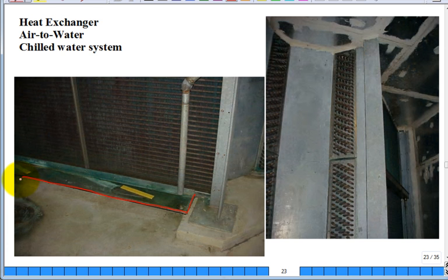What do you think that little tray collects? Condensate. And they put a little stick in there, and they have to be careful of that. They always have these little sticks that the maintenance people go through and put in there. I don't know how long they last, maybe 6 months. And what do you think it's for? Bacteria growth. Yeah, bacteria growth. You'd probably smell it if you didn't have something in there to kill it.